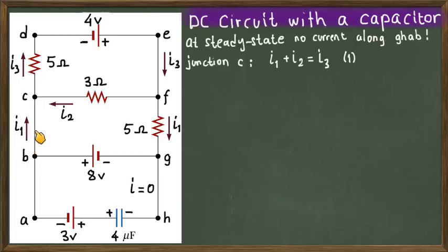Well, setting the directions is initially not very important. It's totally up to you, because once you set up everything and apply the Kirchhoff rules, the junction rule and the loop rules, whenever you find the values of these currents, if you find, for example, a negative current, that means the direction that you initially chose will be reversed.